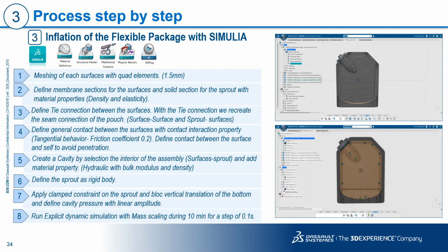So once you define your seals, you need to define contact. What we have in Simulia, the Abaqus solver, is what we know as general contact, where basically you don't need to define all the contact definitions individually. You can just automatically say include contact for the whole domain, and that makes it much easier.